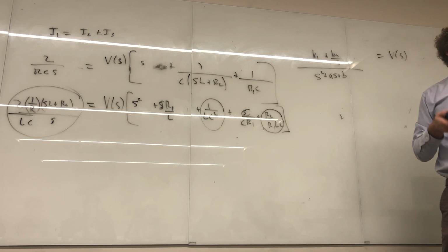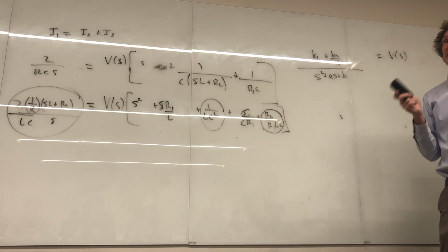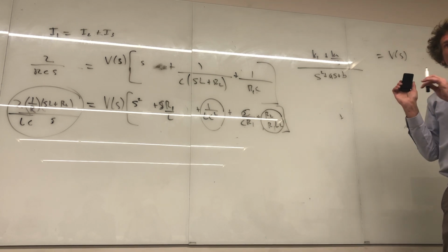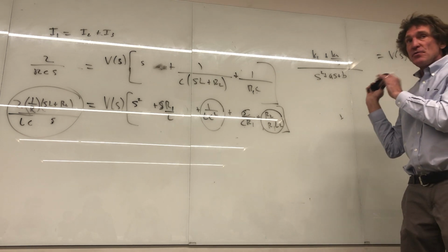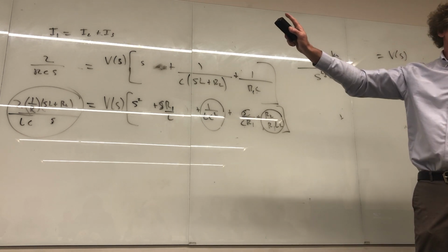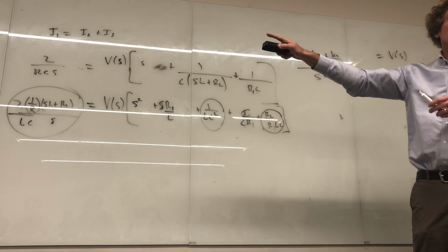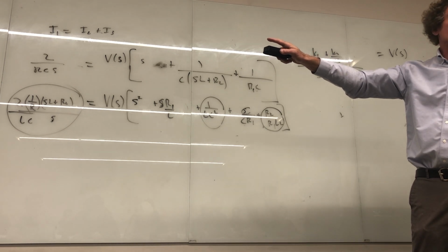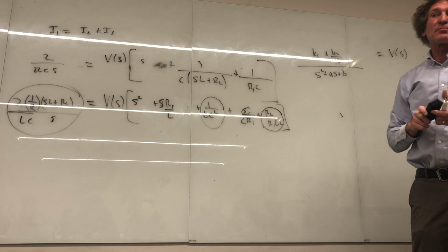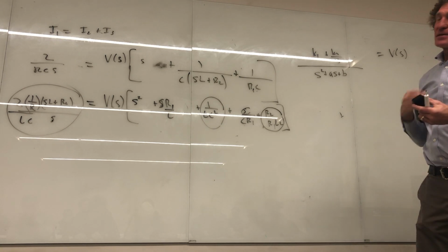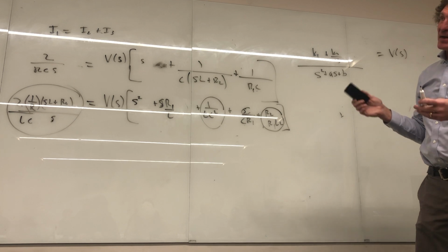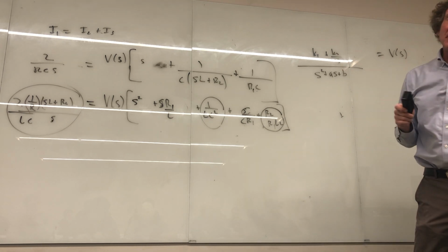All right, I can't do most of that in my head. The stuff I give you, you can do in your head. It's like 2 times 1 problems. They're not going to be bizarre like that. But what I wanted to show you is that the way you get at this is by using S-domain analysis. You turn everything into its equivalent S-domain impedance, and then apply your circuit analysis techniques. This particular problem is a little bit annoying because of the numbers they chose, but it serves the purpose to show you how to do it.